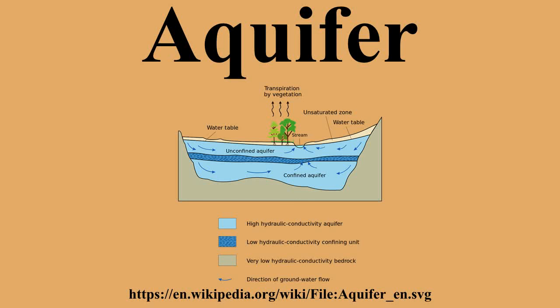Confined aquifers have very low storativity values, which means that the aquifer is storing water using the mechanisms of aquifer matrix expansion and the compressibility of water, which typically are both quite small quantities. Unconfined aquifers have storativities greater than 0.01. They release water from storage by the mechanism of actually draining the pores of the aquifer, releasing relatively large amounts of water.